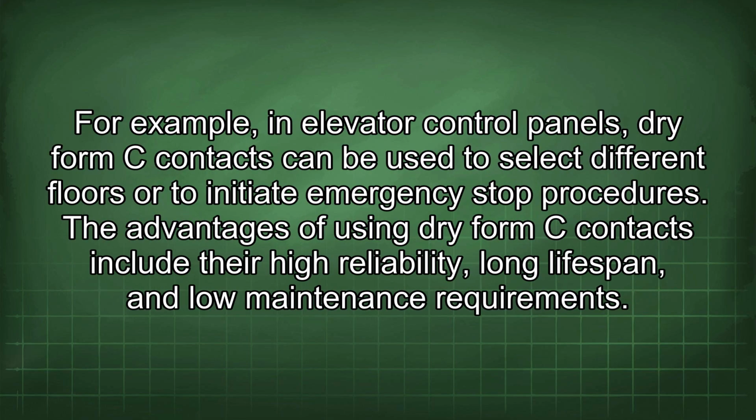For example, in elevator control panels, dry form C contacts can be used to select different floors or to initiate emergency stop procedures. The advantages of using dry form C contacts include high reliability, long lifespan, and low maintenance requirements.